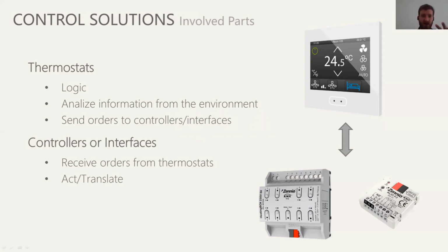So what we were saying a second before, PI, PWM, or two-point hysteresis, that's just a piece of logic. It's not an actual device. It's not necessarily a SET35, as you can see here. This is a user interface of a thermostat, but it's not a thermostat itself. The thermostat itself can be inside the SET35 or inside the heating box or inside any other device.